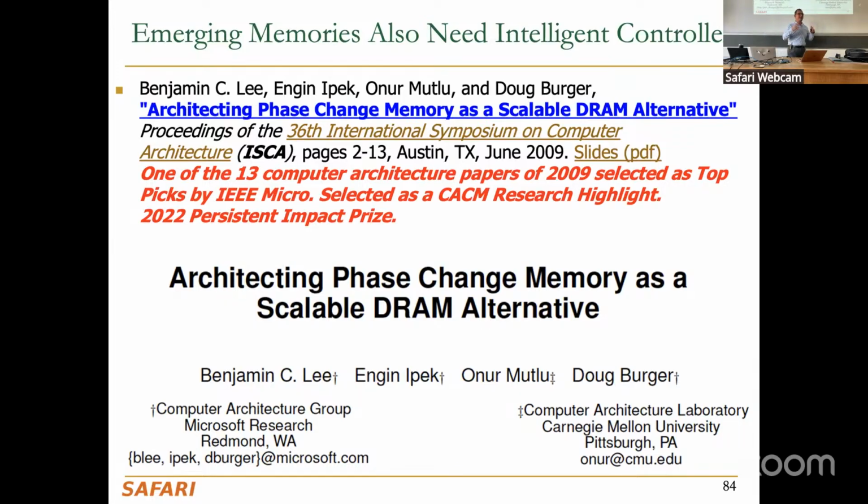But some other memories are very well known, like flash memory. Depending on the technology, depending on how much data you pack, you do 1,000 writes to a cell, and after that, you should not do more writes. Phase change memory is another example. This means that fundamentally, you do need an intelligent controller to manage this memory, right? Because how do you ensure that you don't do more than n writes to a particular location? You need to design a memory controller that understands how many writes you do, and at least tries to avoid doing more than n number of writes to a location. So that's one of the reasons why these technologies actually require intelligent memory controllers from the get-go. And flash memory actually has always needed an intelligent memory controller for this reason, right? For other reasons also. So it's good to think about different memory technologies, and we're going to look at those also.